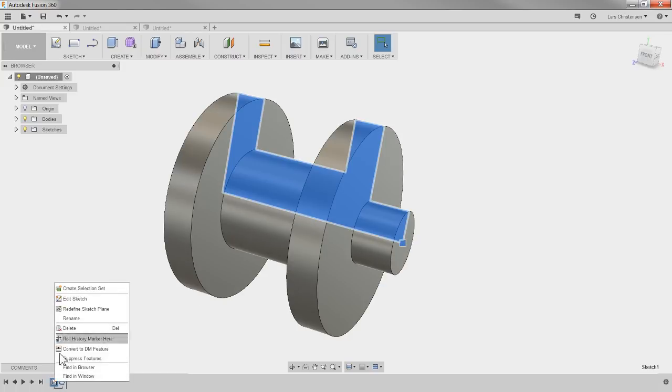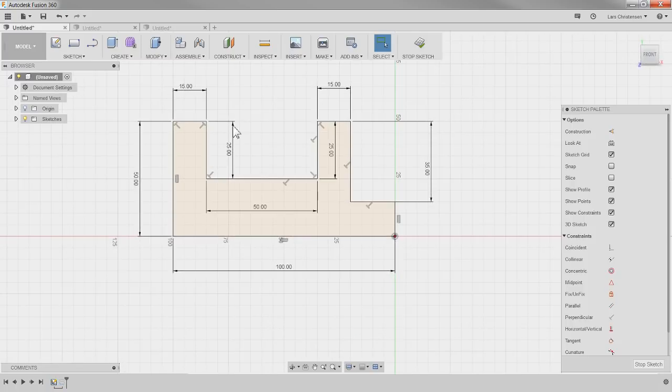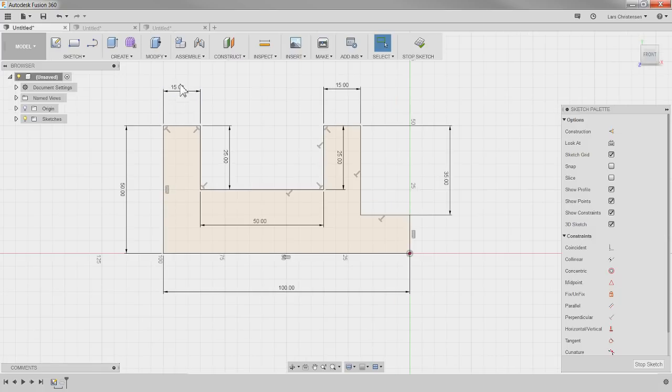But if you go in and you look at this sketch, there is a lot going on in here, and you could actually start just within this sketch to start saying, well, if we know that these 2 pieces here will always be 15, we don't need to have 2 dimensions. Same thing with these 2 should always be 25.